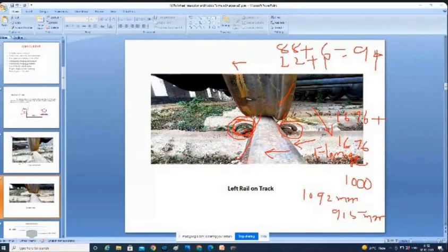At the time of derailment, if a clip is missing, you have to understand that the gauge is likely to have increased in that particular area. But practically, whenever we go to the derailment spot, by that time the engineering persons will have fitted all the Pandrol clips. That is a different story.